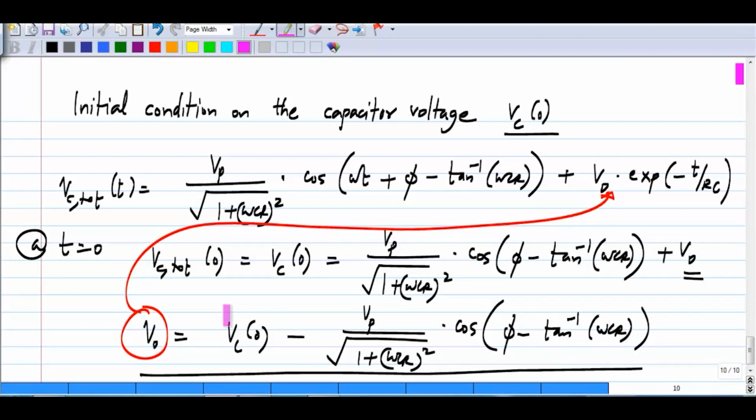Okay. So if you start from the right initial conditions, and what the right initial conditions are is specific to the input you have, you can have no transient response and you will immediately get the steady state response from the circuit. And sometimes in circuit design this is useful. You don't have any transients, you start off the circuit from the right state so that you will have only the steady state response. Okay.